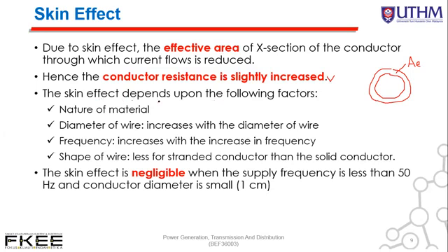The skin effect depends upon the following factors: the nature of the material, and the diameter of the wire; increasing the diameter will increase the skin effect. Frequency: an increase in frequency will also increase the skin effect. Finally, the shape of the wire.